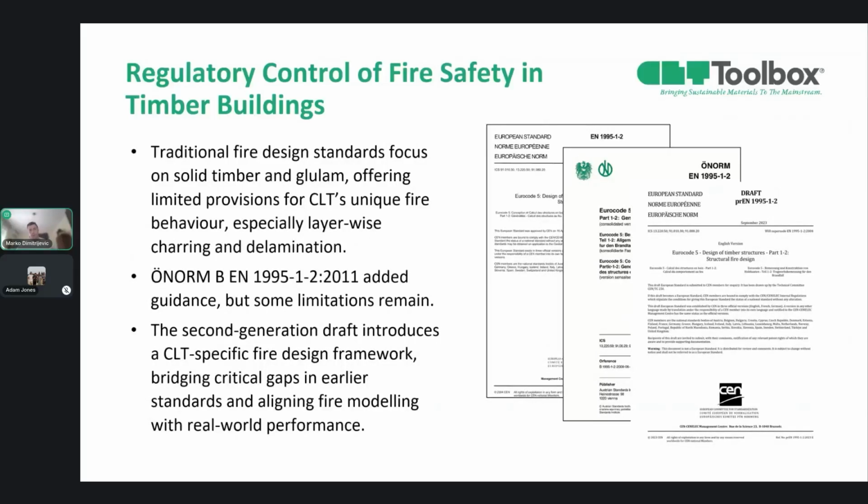So here's just an overview of existing codes. Traditional fire design standards focus on solid timber and glulam. That is part of the current Eurocode 5 for addressing fire. But there is a limited provision for CLT, or in particular for the basis of Eurocode, there is no provision for CLT and its unique fire behavior.